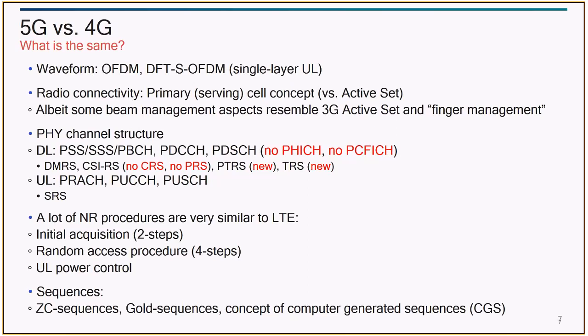In the time domain, they get repeated once every 120 milliseconds for a 5 millisecond window. But in the frequency domain, every 900 kilohertz, you would see the PSS, SSS. As you go all the way up to millimeter wave, you would see this frequency separation getting increased to about 2.4 megahertz instead of the 900 kHz. But there is a certain amount of scaling.